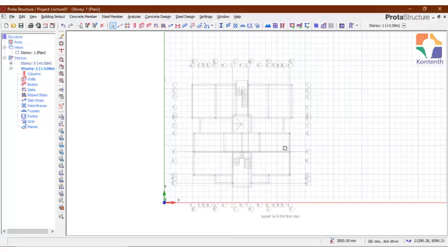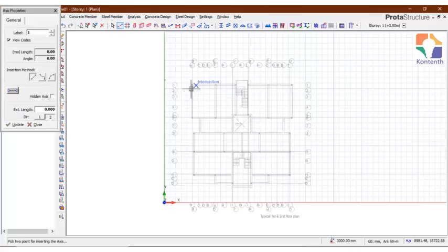So as it is now, what do you do with this? What you do with this is just pick your axis icon and snap to wherever you want to put your axis. Just like you created the axis the first time using the axis toolbar. Here you have the axis property. Which axis do you want to insert at the moment? You want to insert your direction 1 axis, or you want to insert your direction 2. You select the applicable one.